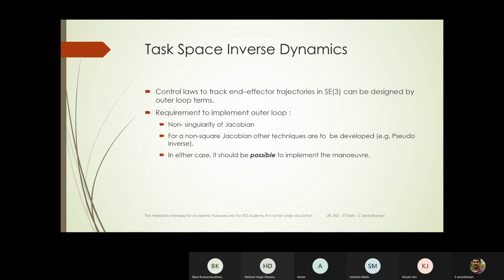Okay. So in conclusion, when you are doing your control design in the joint space, there is no ambiguity of how the joint should move, because the torque is directly affecting the acceleration of the joint. There is no ambiguity in how the joint will move if you give the specification in terms of the joint itself. However, when you are giving your specification in the task space, it becomes more unclear, because now there is an additional condition that whatever trajectory is being given, XD in the task space, should be possible.